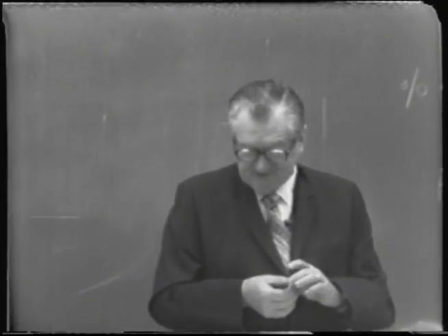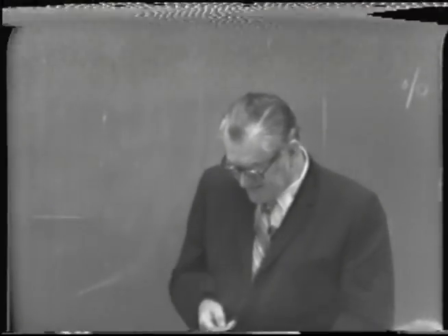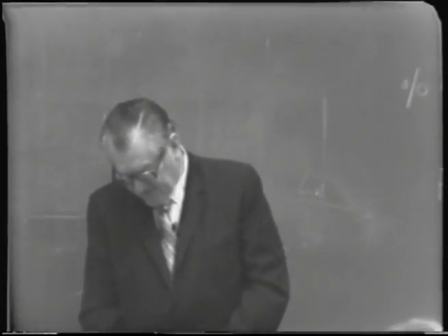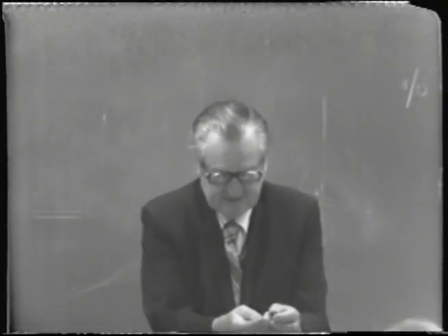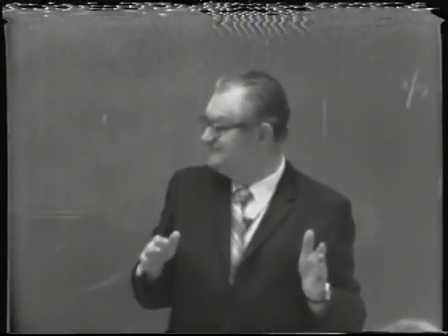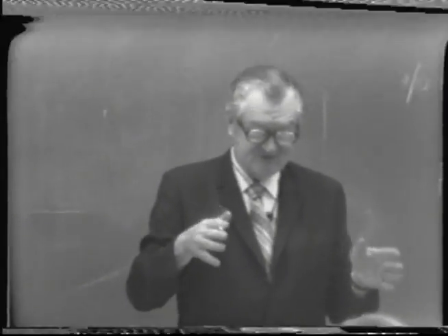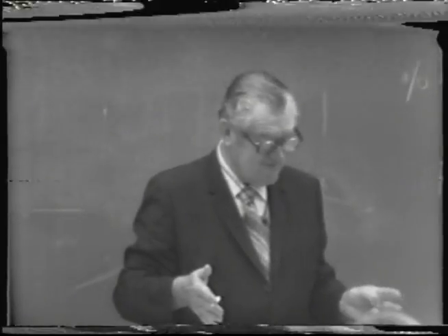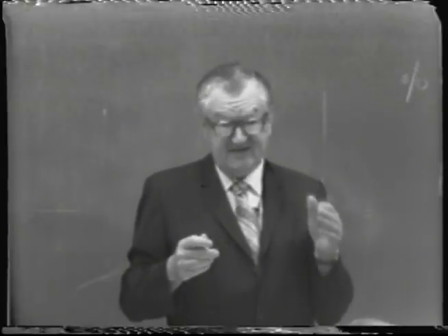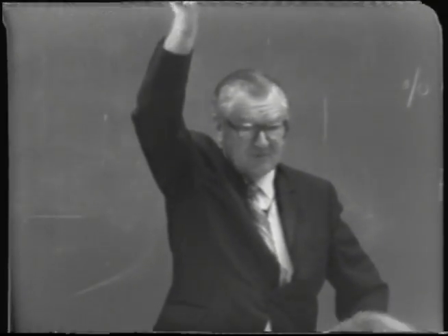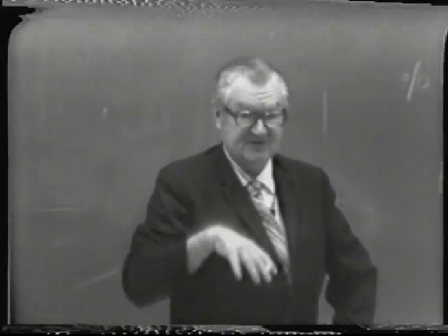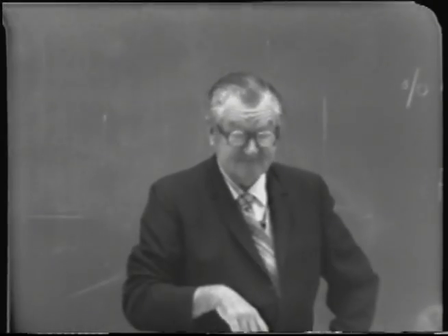This particular aspect resulted also in the practices I'll talk about in a later period of splitting the column into sections and putting it into two pieces down on the floor. In other words, you can take a distilling column, which fundamentally consists of a concentrating section above the feed and the stripping section below the feed, as we already know, and you can make it in one single column.